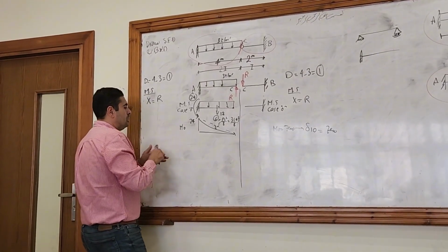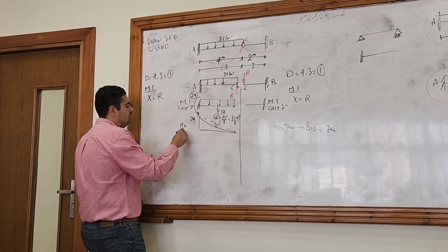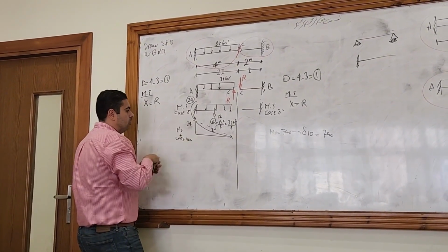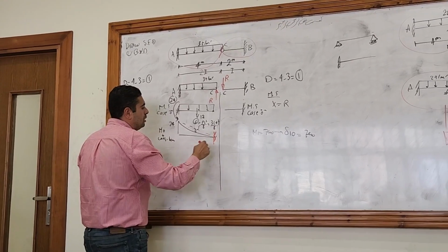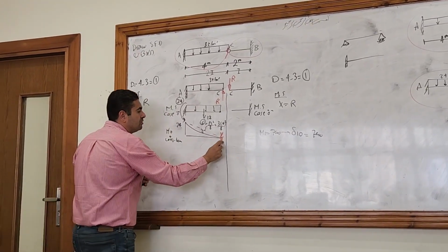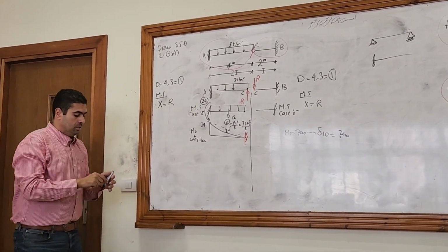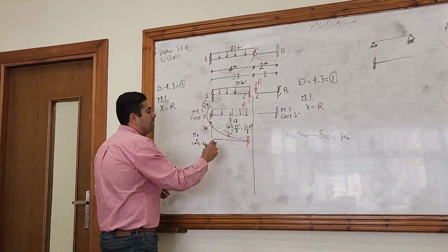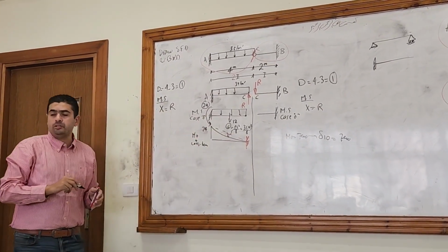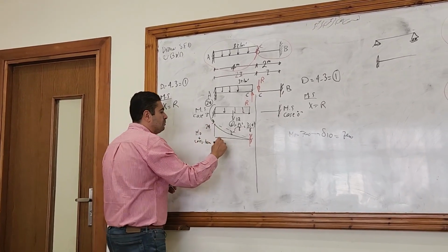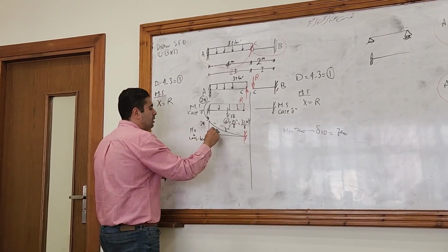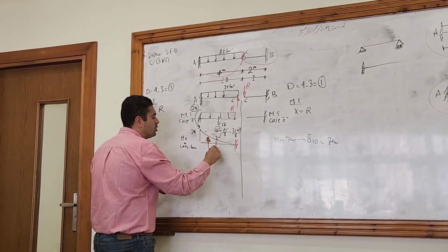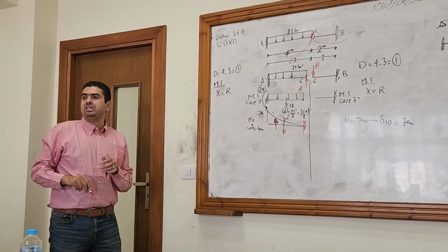Put the moment on a conjugate beam. Fixed will be free, free will be fixed. I now need to calculate the moment here at C. What about the areas? A triangle, the same like the last example. A triangle above the datum, so it will be upwards. And the parabola, which is subtracted, so it will be downwards in the middle.